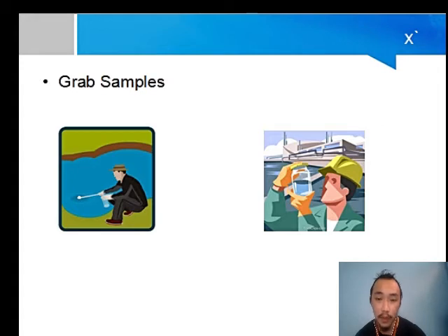Of course, the cup and bucket method just described is only an example. You wouldn't actually sample wastewater in that way. A grab sample is typically taken manually, but some automated samplers can be programmed to take grab samples for you. Grab samples are taken for extreme conditions and for batch discharge operations. Grab samples are preferred for reviewing pollutants that change quickly with time, such as pH, temperature, and bacteria.